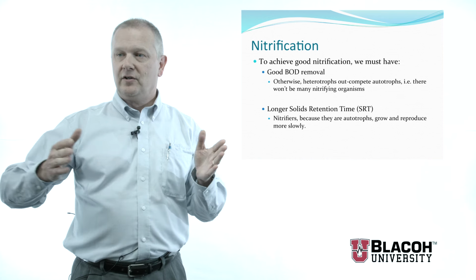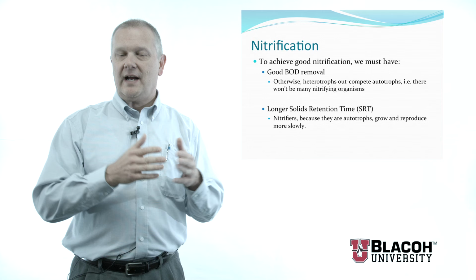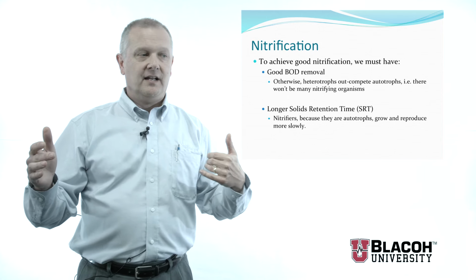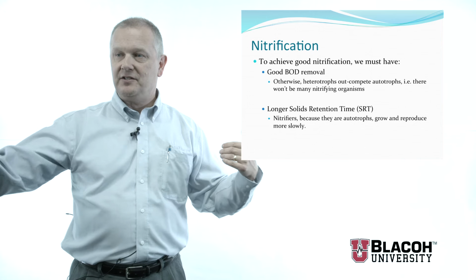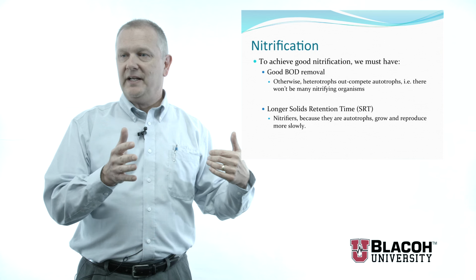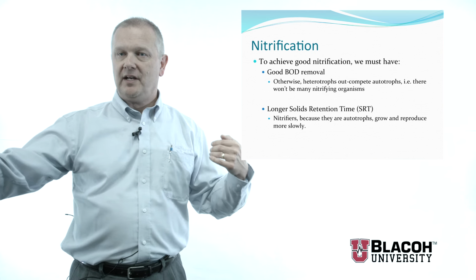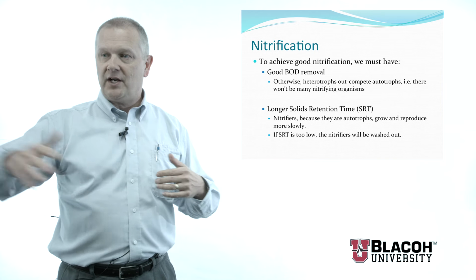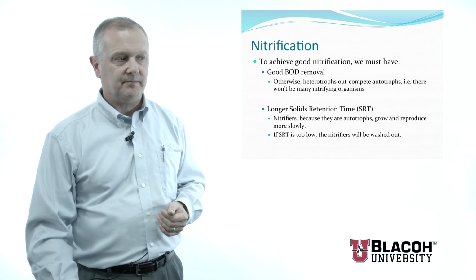you have these longer lived organisms, or actually a longer life cycle organisms, reproductive cycle, and so you have to have your solids in the system for a longer time than you would just to remove BOD. If you want to nitrify, you have to have a longer sludge retention time, solids retention time, so that we don't wash out these nitrifying organisms from the system.